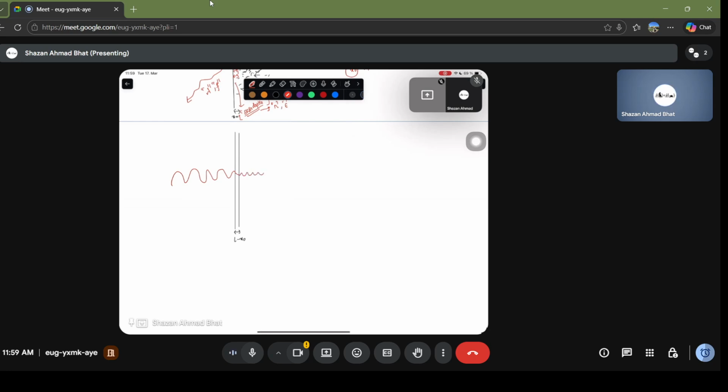other side. So there are different scenarios that happen when the evanescent mode leaks, and it can couple to whatever is on the other side. It can be a semiconductor, it can be another metallic strip. So then there we talk about something called plasmons. We talk about the plasma interaction with the metal, and so on and so forth. We don't have to go into this detail, but this scenario can happen if you make the thickness small enough that it becomes of the order of the penetration depth, then your electromagnetic wave can leak through it.